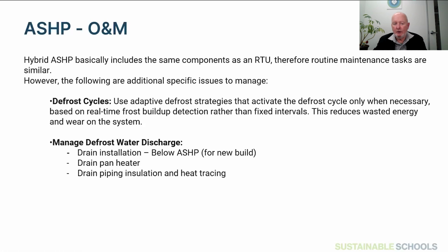If you can run a rooftop unit, you can run these units. They're obviously the compressor condenser are going to run more than they would with a conventional unit. The defrost seems to be the biggest issue that we've heard so far, is one, optimizing it so that it doesn't cost too much, but making sure that the water that comes off that in the middle of winter doesn't end up in places where the ice is going to cause some damage. So the only significant operational concern we've seen so far has been around defrost, and these notes, I think, Mark, capture this really well. Next slide, please.